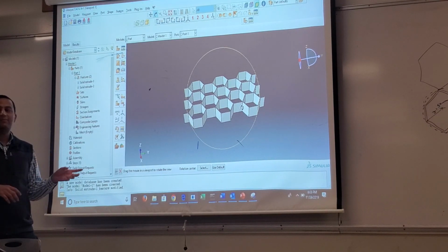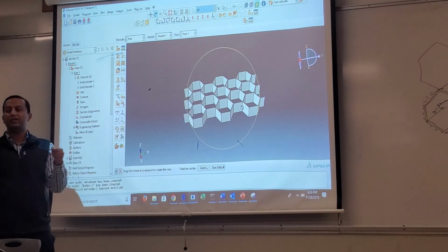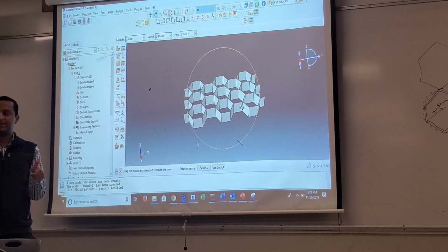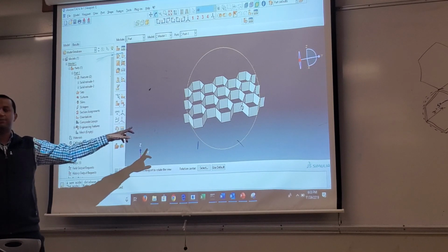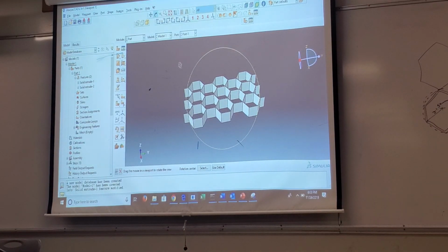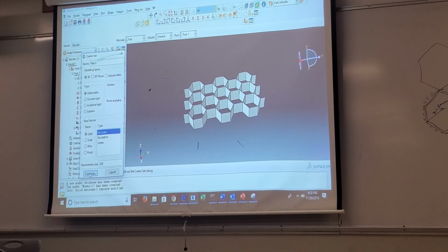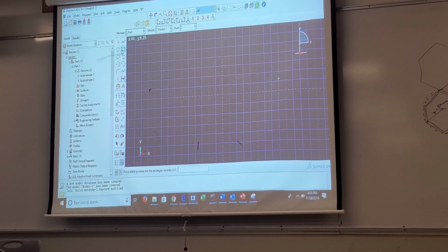I'm going to create impact simulation, you are going to do the same thing with me, but I will be doing on this, you will be doing on the flat plate. Make sense? So part number 1 that is done with me, it is not available with you, but let's start with part number 2, which is a composite. So part number 2, extrusion again, solid part, plain rectangle. Now, what is the dimension of the rectangle I should use? Let's take a dimension of 100 by 150 millimeters.